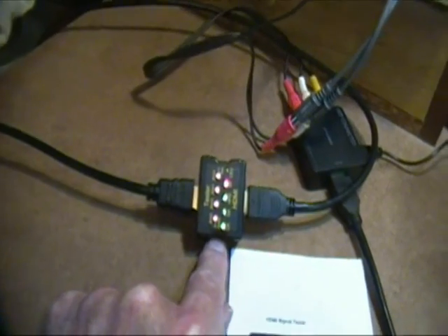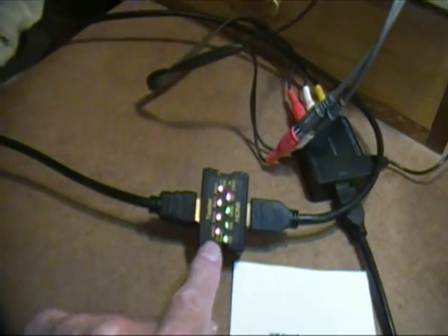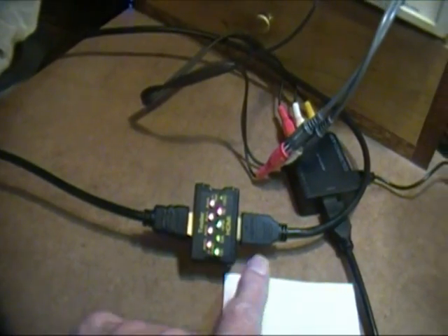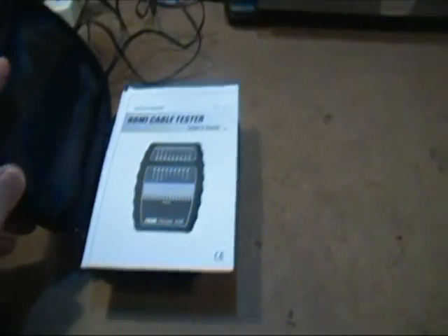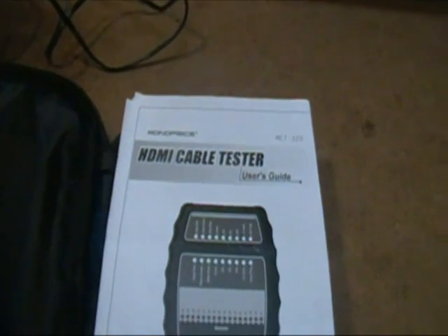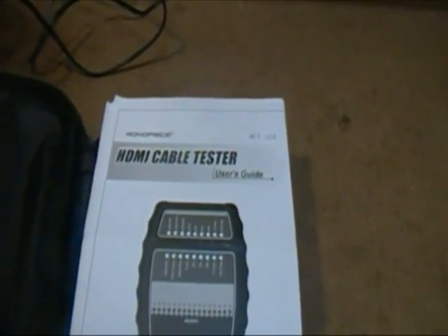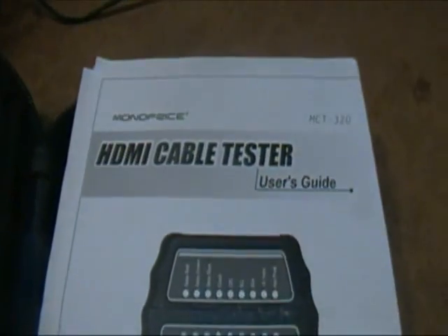The reason that I point out that this is a signal tester, not a cable tester, is although it will allow you to test cables, you have to use it on a working system. There are a number of cable testers, and I'll show you one of these in a minute. Never plug one of these cable testers into a working unit. They're not intended to monitor the HDMI signals. They are only intended to test cables. And so you notice this one says cable tester. This one says signal tester.